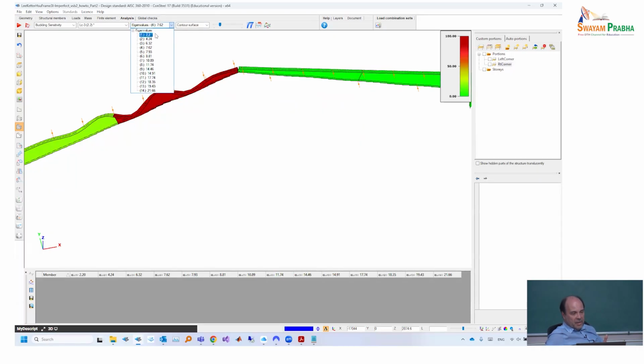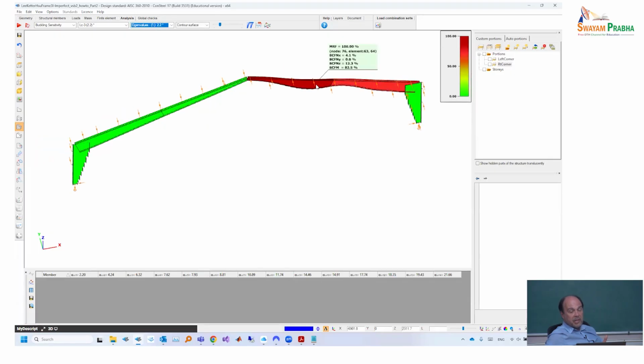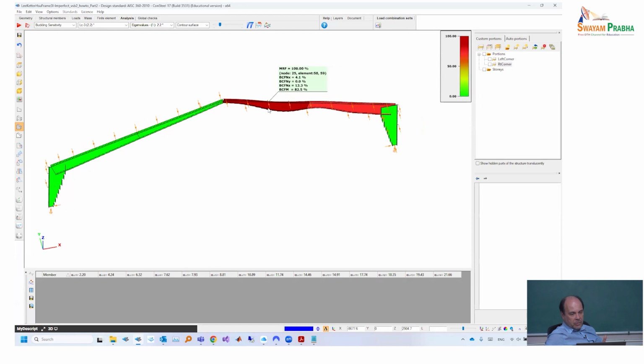Okay? If we go to the very first mode, which is valid for this rafter, as we saw already, it is clearly for this part of the rafter, where visibly also there are the biggest waves, but it has almost 100, it's 83% mode relevance factor on the lower rafter, so obviously this will be also assigned.